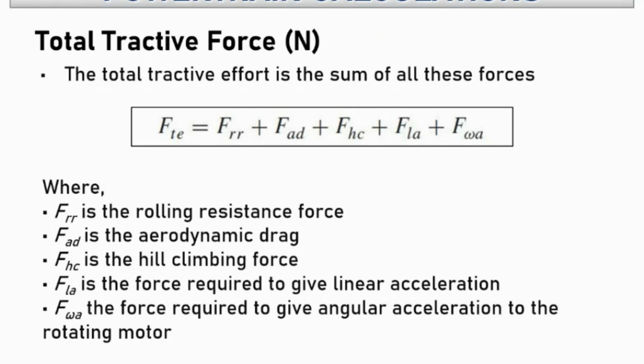You said it, yeah. Like we saw in the previous slide, with the force we are going to find out the torque required, and with the torque we are going to find out the power that I need to propel my vehicle, and with the power we are going to look at what should be the power rating of a motor. Now we are going to choose a motor by doing a physical hand calculation of all these forces that we should overcome. What should be my torque?